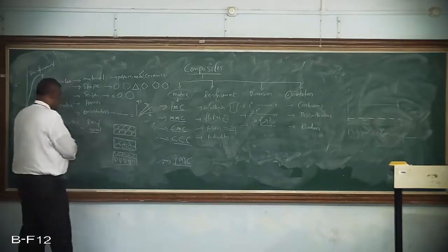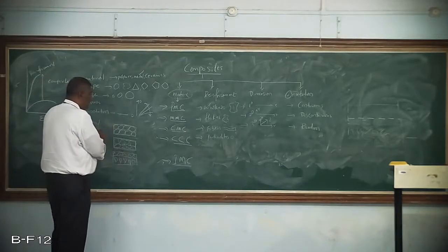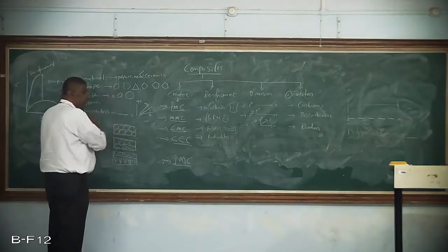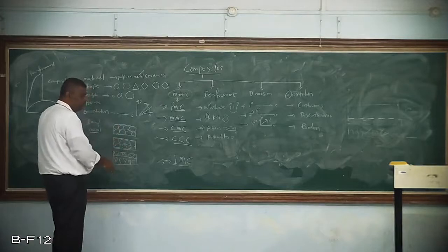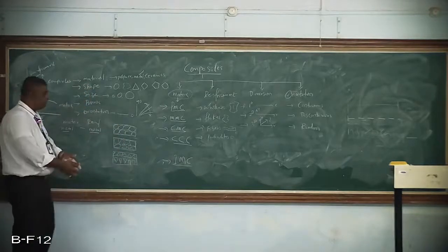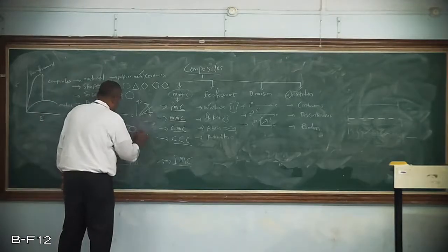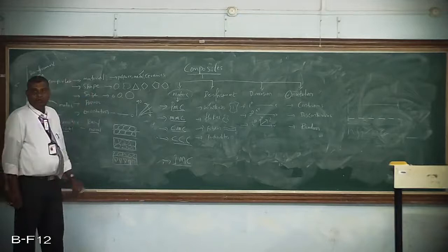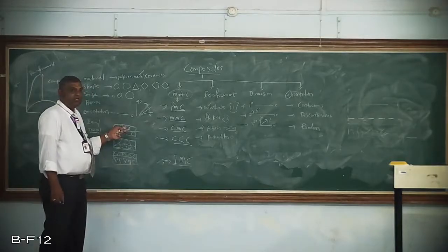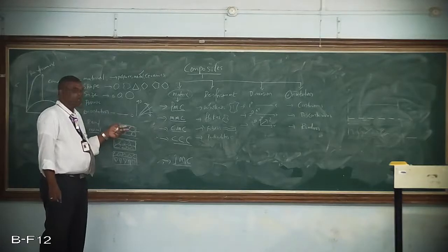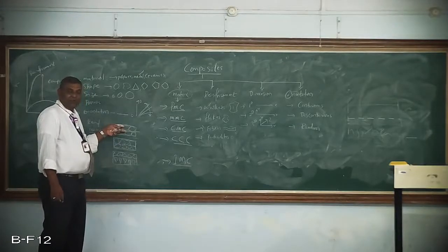So now I have fixed metal and metal. So this metal is having this type. Though the material is the same, by changing the shape, spherical, irregular and regular, the property will be different. So this is considered to be the weakest because here you form a slip plane, because it is having a regular boundary. In this the slip will be more, and when the slip is more the dislocation is more, hence the sliding will be more.